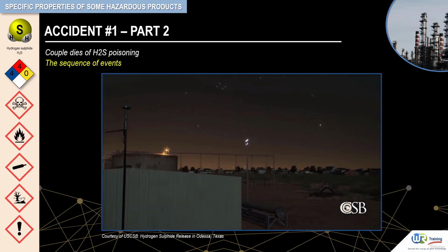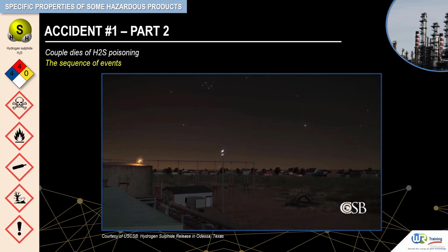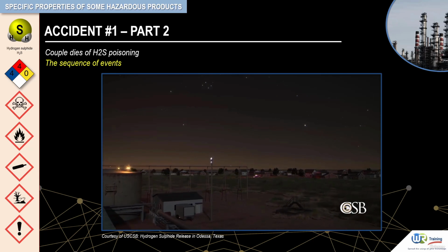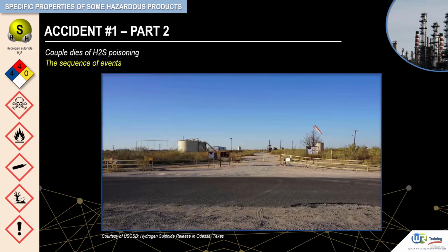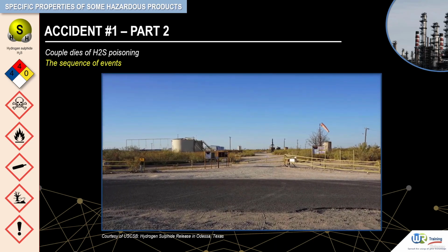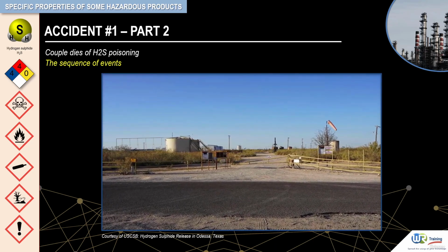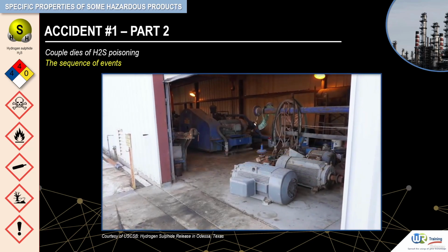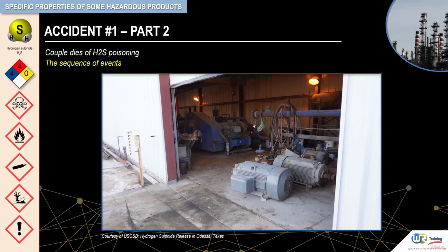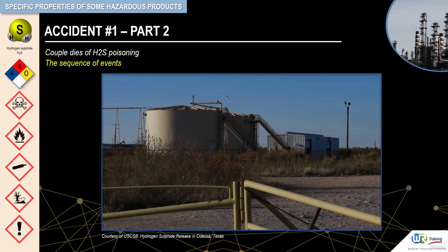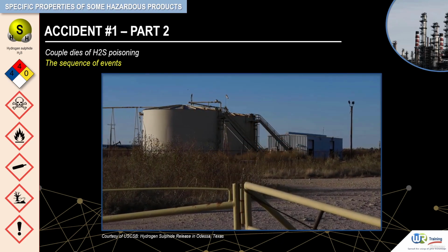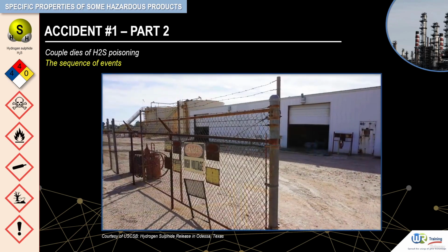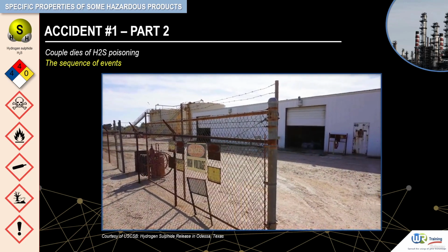A short time later, emergency responders approached the pump house. They detected a very strong smell of hydrogen sulfide. This required them to set up the command post outside the front gate of the facility and wear self-contained breathing apparatus. They found the pumper and his wife deceased inside the pump house and water spilling from pump number 1. The responders rescued the 2 children who were inside the spouse's car. Working with Aghorn employees, they were able to stop the water release the following morning.